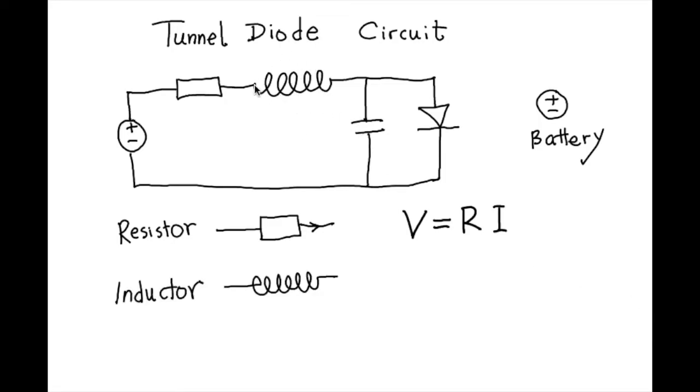And this is an inductor. Again, if we denote the current flowing through the inductor as I, and the voltage decrease along the direction of the current as V, then V and I satisfy this equation. Here the dot means di/dt, so differentiate I with respect to t, and I dot is the rate of change of the current. L is a constant, a number, called the inductance of the inductor.